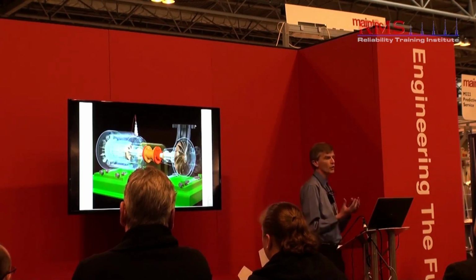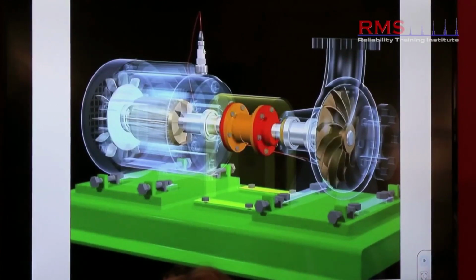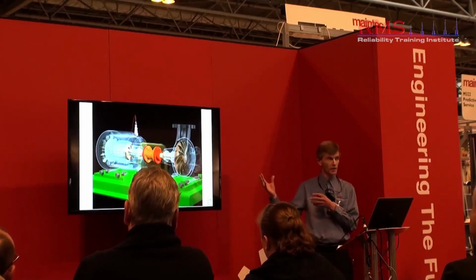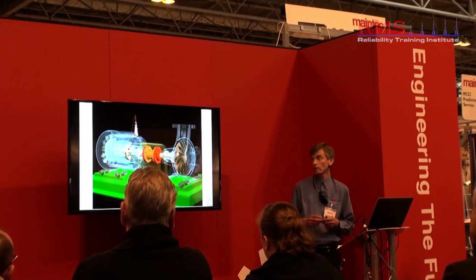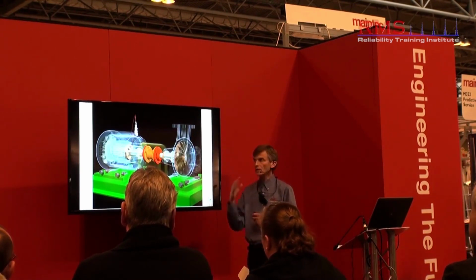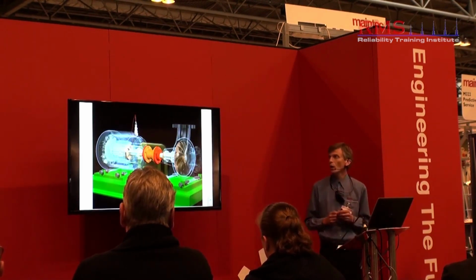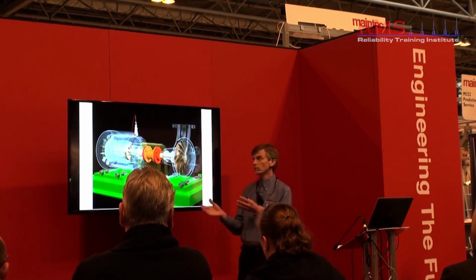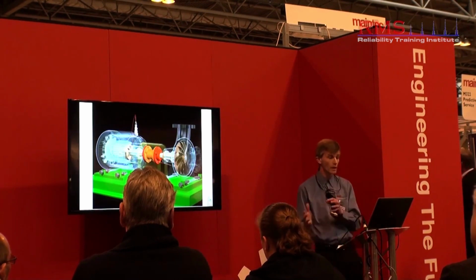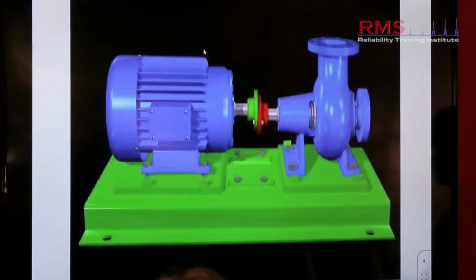The forms of vibration that we measure at this particular location could be electrically related. They could be mechanically related to different parts of the machine itself in a mechanical context. We'll talk about those in a moment. And thirdly, there could be a process vibration. So whenever we take a vibration measurement to measure the health and try to track the health of an asset, all of those different considerations could be measured through the signal. And we can separate them out to understand which part of the machine, is it process, is it electrical, or is it mechanical problem we're dealing with.